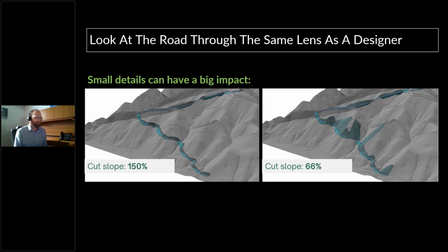And when Jeremy was discussing colluvium slopes, it's one of those things that if you can recognize it early in the planning phase, you can say, well, either I want to take a closer look at that, or maybe I can recognize that that landform exists. I'll change my cut slope angle to be appropriate, even at the planning stage.